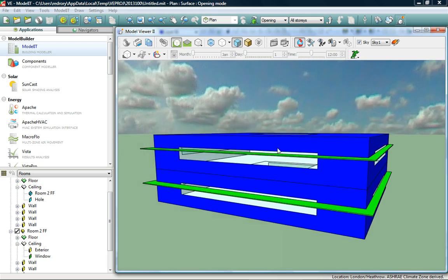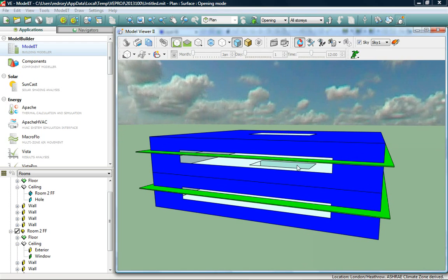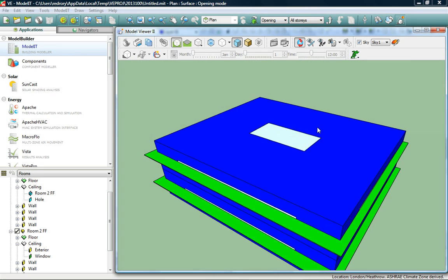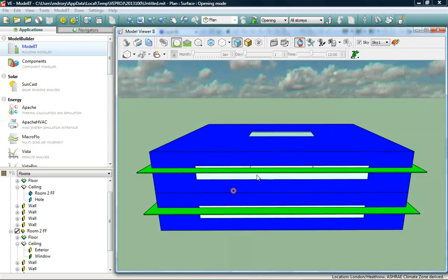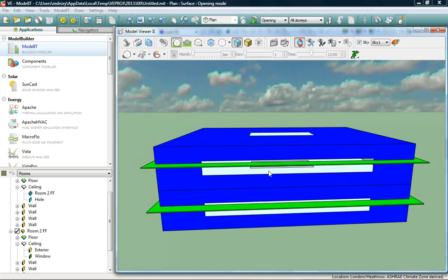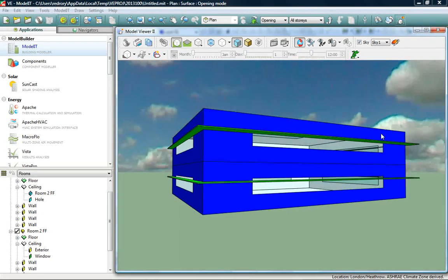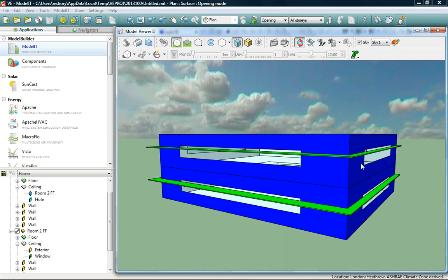So using the left button I can pan around. So as you can see, inside there's a hole, and on the roof there's a glass window inserted. They look very much the same, but holes can never be added on the external fenestration. It'll cause the model not to work properly. Just keep note of that. So you can see the solar shading and the windows are in place.